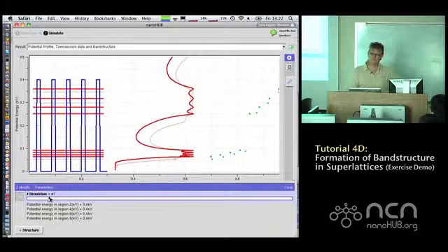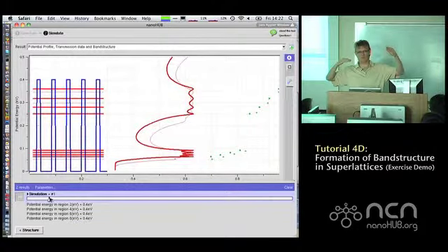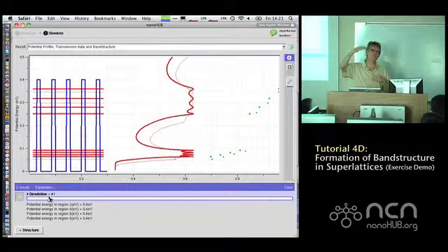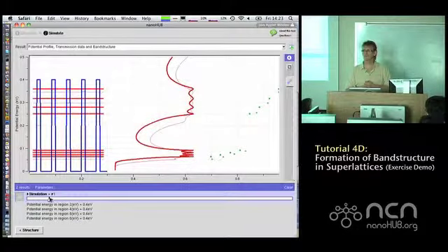Seems like I increased the width like that. And why would you do such a thing? Well, if you actually applied a voltage of that much voltage difference over the barrier height, they might end up being roughly of the same height, and you might end up with a more symmetric structure again. So some people want to build a superlattice, they want to build a mini band, but they want to make it a symmetric mini band. That means they need to chirp the barrier height in order to compensate for the voltage drop. So you can play with things of that nature.